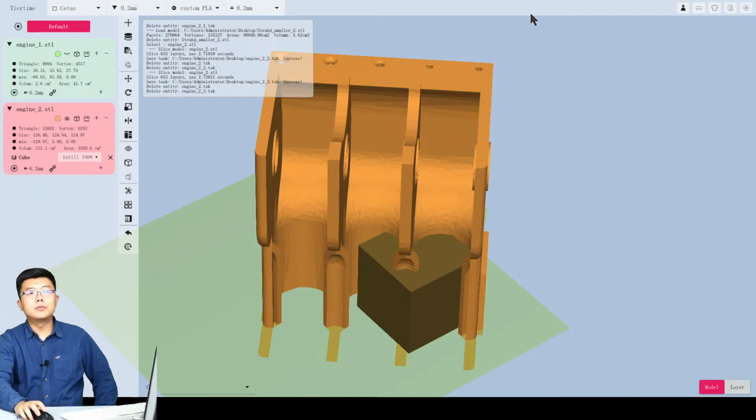Yep, for the printers which are too old, UP Studio 3 still does not support them, because we found that with firmware version 322 or earlier, the software will cause the printer to pause randomly, just like UP Studio 2.6.